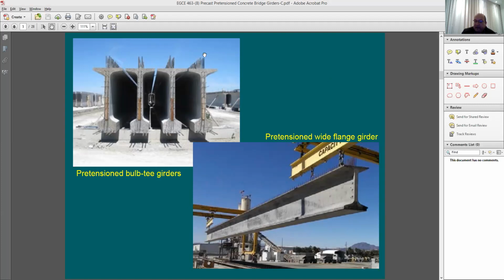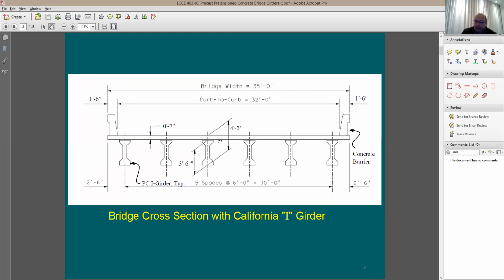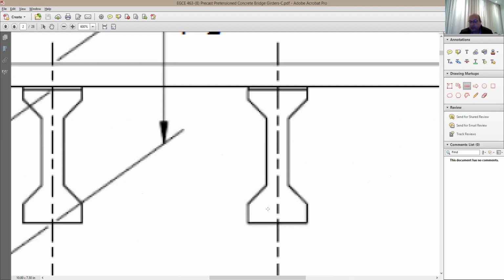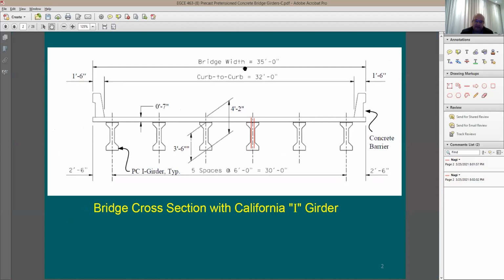And you see these rebars, the dowels. This is because if you go back to the bridge section, now you'd like to connect this bridge deck, or concrete slab, to the beam itself. And your only chance is to have some dowels between the two. That's why you see some rebars that go like this in both sides. Right? Sometimes you have it also with some hooks. And then you put some rebars in the deck, and then you put the concrete deck of the bridge, and with that you have good bond between the beam itself and the deck.